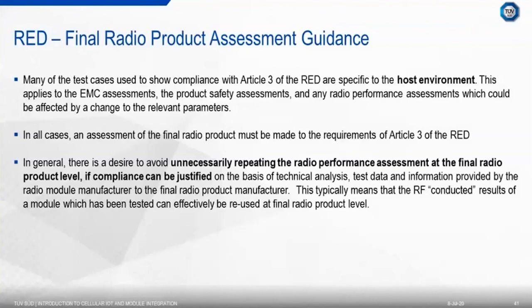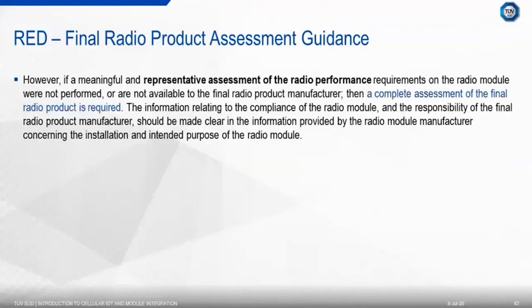And that's really driven the need for module manufacturers to assess the radio performance, which effectively allows the RF conducted portion of the radio module compliance to be used at final radio product level, which is obviously great news for module integrators. If there's no assessment of the radio performance of the module, or this information cannot be obtained by the final radio product manufacturer, then a complete assessment of the radio performance is required. Any information relating to the compliance of the module and the responsibility of the final radio product manufacturer should be made clear in the information provided by the radio module manufacturer in relation to the installation and the intended purpose.